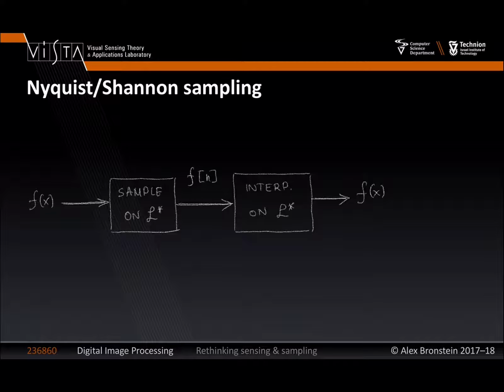If it is not, so let me draw a geometric interpretation. This is the space of band-limited functions. Of course, it is an infinite-dimensional space, but I'm given only a two-dimensional screen, so pardon me this limitation. If my function lives here, the orthogonal projection, phi adjoint phi, keeps me within the same space. It will be the same vector. If my function is not band-limited, this is my function f, I'm going to orthogonally project it into this space. So this will be the outcome of the projection. So I'm not going to reconstruct my function exactly anymore. I will reconstruct a band-limited version of that function. Okay? This will be my projection. Any questions?